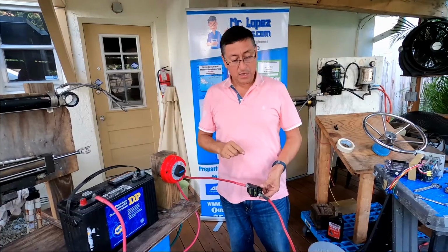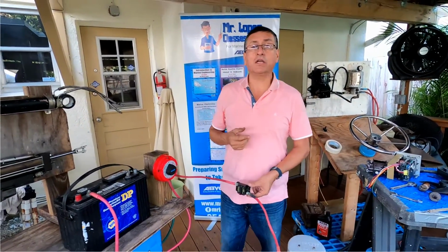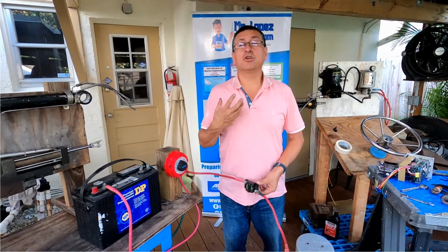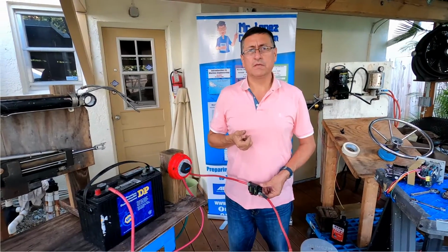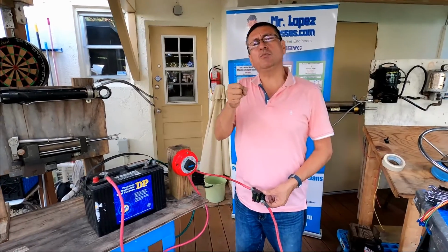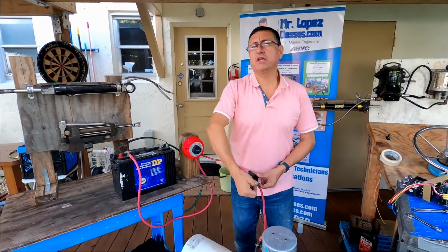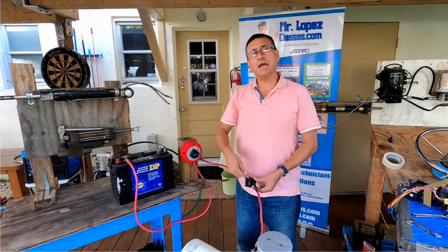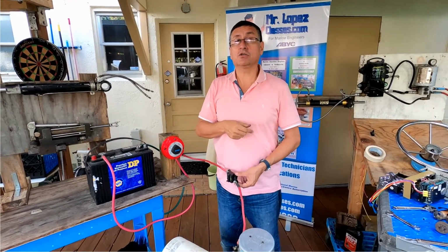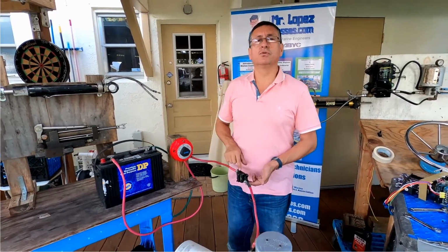Let me explain why. When the bow thruster is working, what happens if the bow thruster sucks in debris, plastics or cables? Immediately the propeller is locked. If the propeller is locked and you continue operating the motor with the joystick, probably the temperature increases dramatically, you melt the cables, and you explode the battery and the solenoid control box also. In order to avoid that inconvenience, this fuse is important.